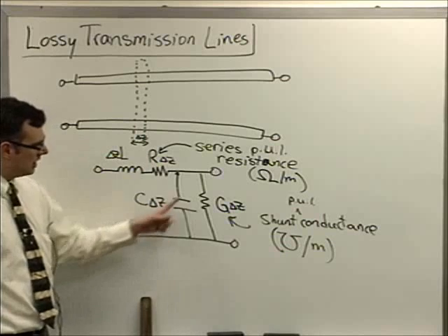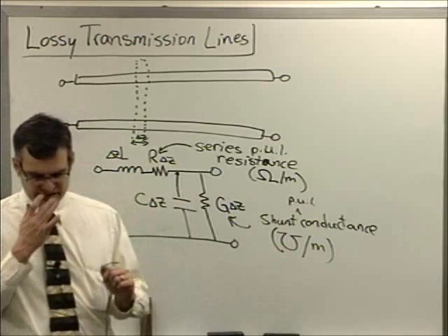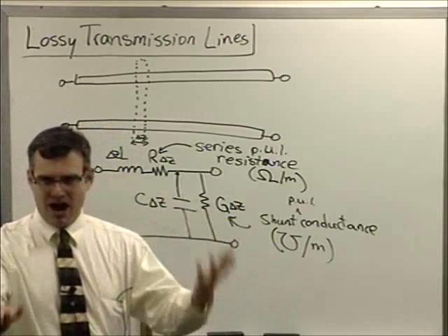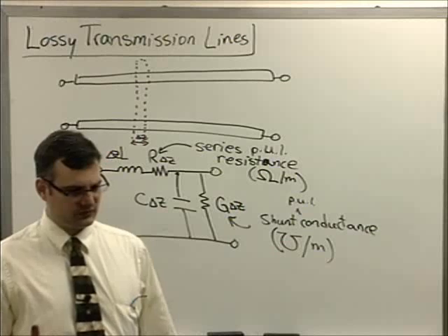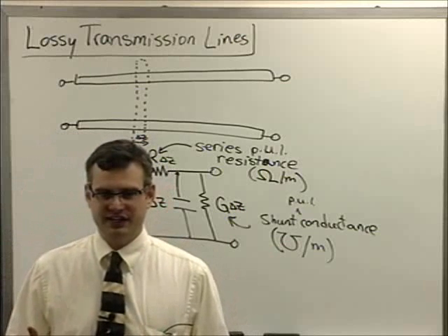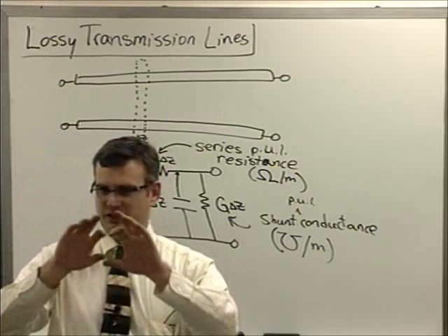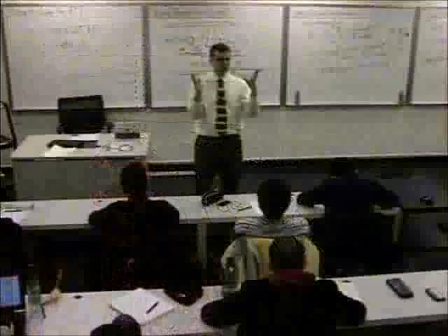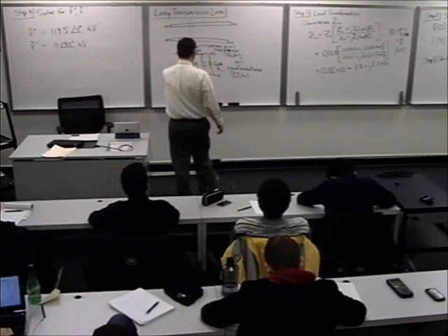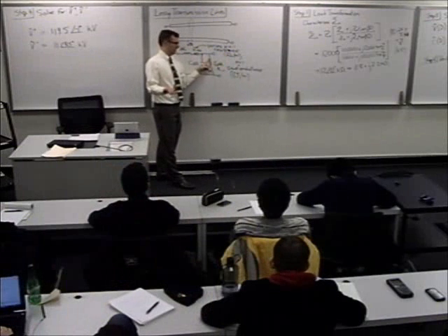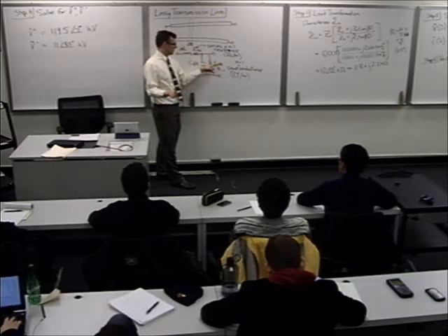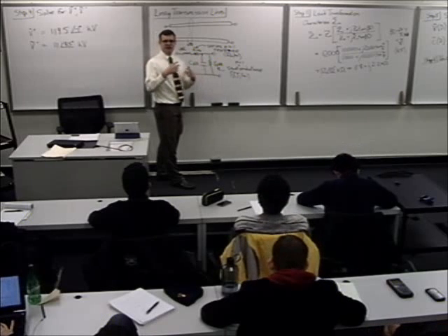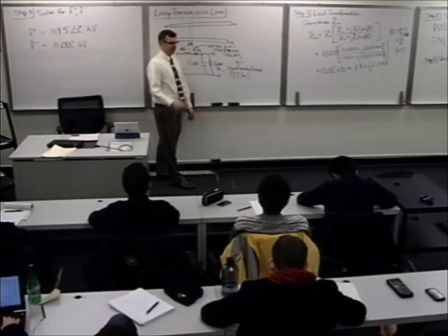That's relatively straightforward. What causes shunt conductance on a transmission line? There are a couple different mechanisms that we all model with a shunt resistor in place. It could be some leakage conductivity in your dielectric. If your dielectric material is not a perfect insulator, if it allows for a slight amount of conduction current to and fro, then there could be hopefully a very large resistance value, a very low conductance value for that shunt conductance. Hopefully it would be such that you could ignore it completely. There are some instances where you have maybe imperfect dielectrics where you actually do get some shunt ohmic losses.